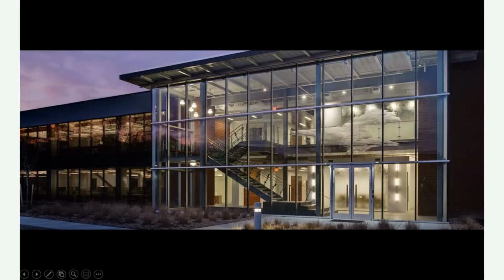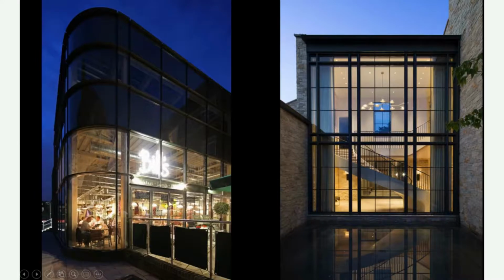Here's another view. And you might get curved glass, and you can see it's kind of difficult because this whole roof and all the water and all the snow, whatever you get on top, has to be transferred to the ground, to the foundation. So that's what these aluminum columns are doing. You got to find some way of taking the loads off the windows and down to the ground. Same thing over here. Roof loads go to these columns, down to the ground.